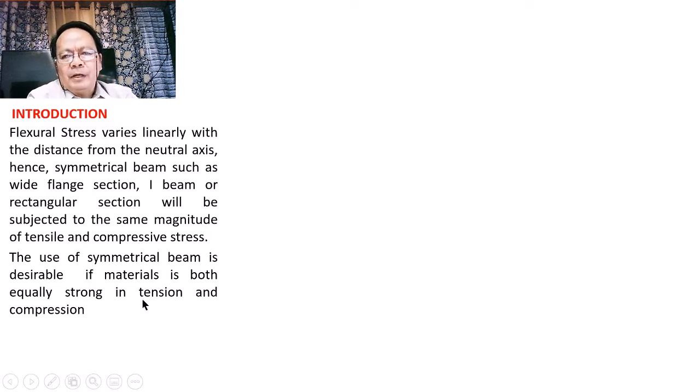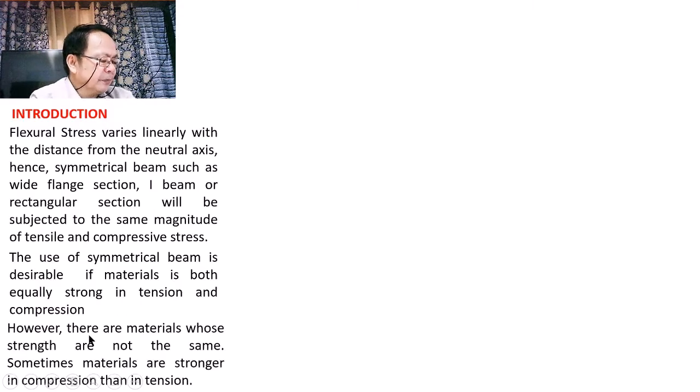So sabi nga, yung design ng symmetrical beam is really desirable if our materials are considered to be equally strong in tension and in compression, if they have the same capacity to resist tension as well as the capacity to resist compression, then the use of symmetrical beam is really desirable. However, there are materials whose strengths are not the same. Sometimes materials are stronger in compression than in tension.